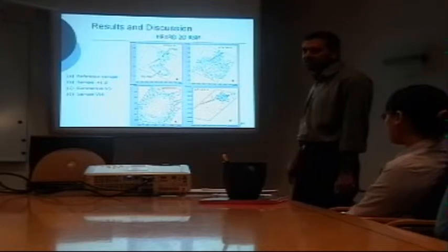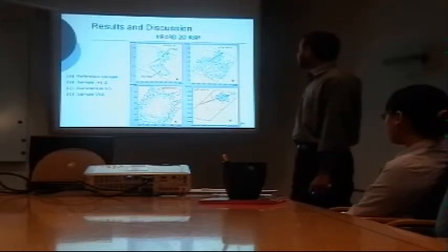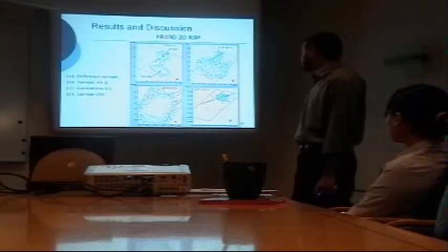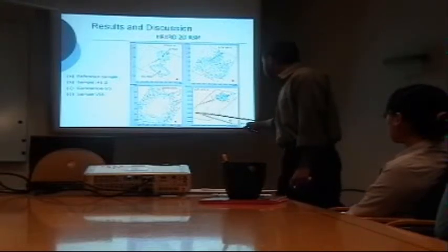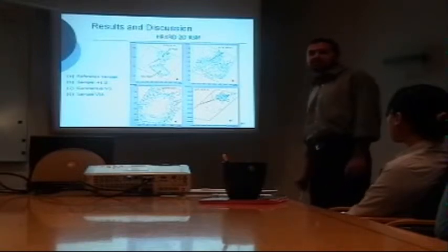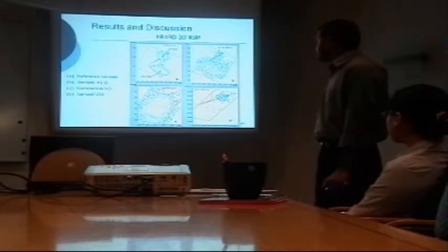In figure D, which shows the sample V38, which has been grown at a very low temperature of 175 degrees centigrade with a high growth rate of 0.8 angstrom per second, we cannot see the silicon germanium peak in it. That indicates that the surface has become polycrystalline.